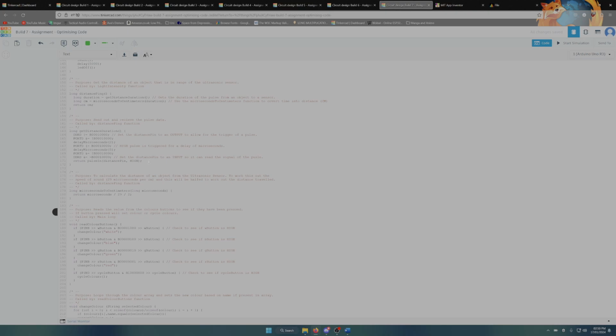The next bit that was changed was the get distance duration. This has all been changed to use port manipulation now, using the data direction register, and using port to state if it's high or low to send the pings. So that is all done this way now.